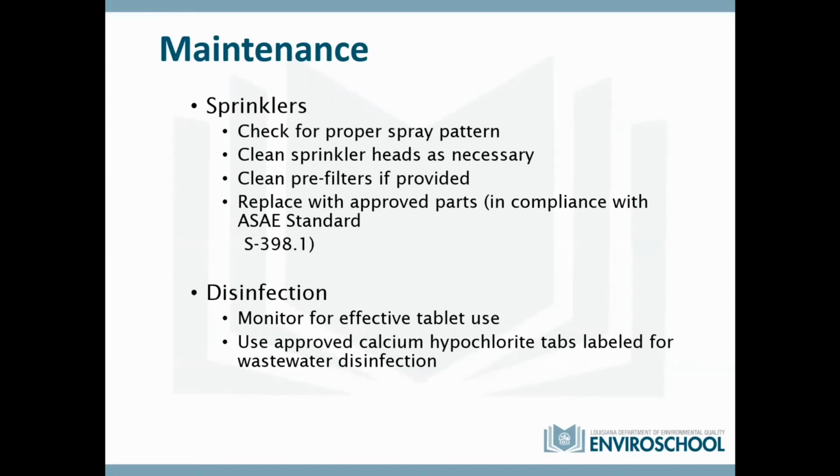Sometimes the sprinkler heads will need to be cleaned. What I understand is they can build up with some biofilm. If they have pre-filters to clean the gunk out before it goes to the sprinkler itself, you have to clean those periodically. And again, any parts that need to be replaced, use only approved parts that are specific to your system.